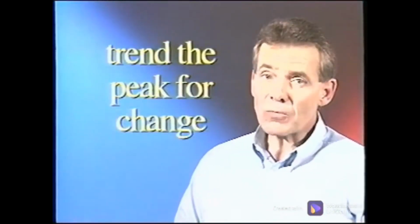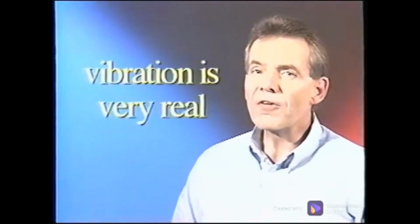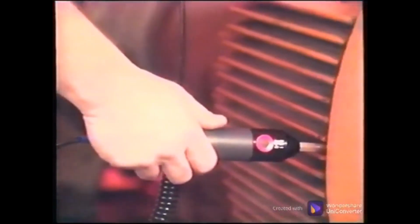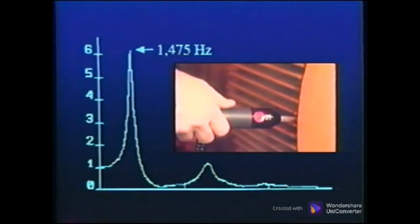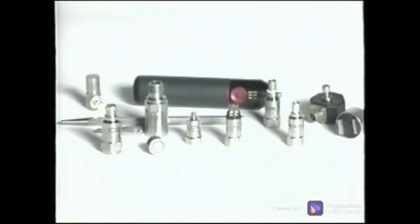The amplitude can be stable at 0.1 inches per second, indicating it may not be degrading electrically, but the vibration is very real, accelerating mechanical failure. Keep in mind that the rotor bar pass and stator slot pass frequencies may be in the resonance range of handheld transducers, and therefore the amplitude will be magnified. Be sure to use the accelerometer and mounting technique that provide an accurate amplitude in this frequency range. After detecting the possible electrical problem in vibration data, follow up with current measurements to confirm the findings and determine the severity.